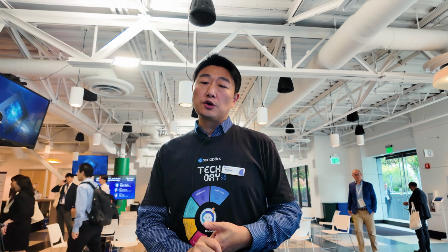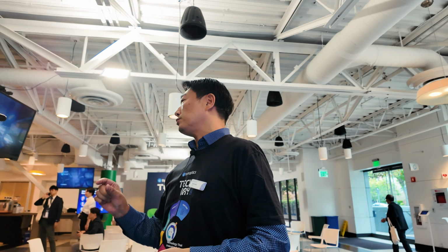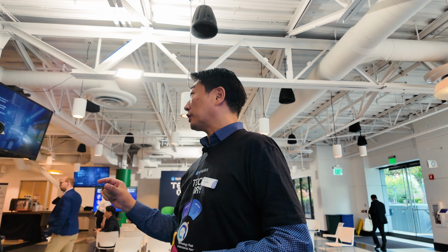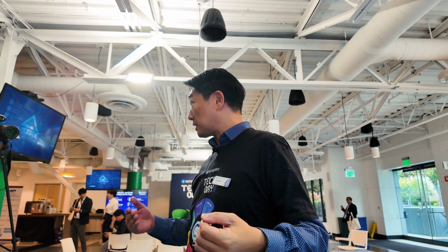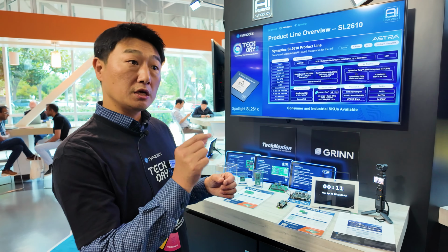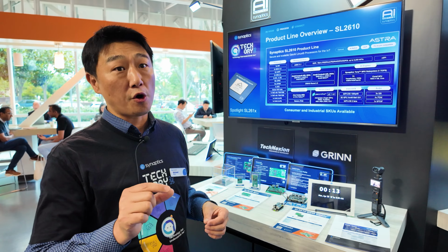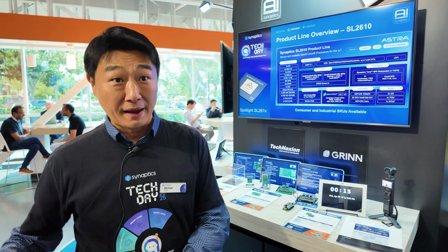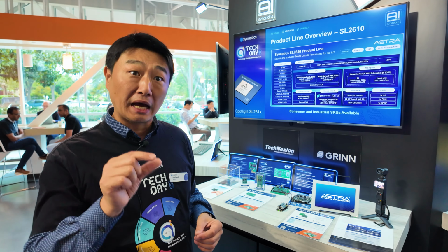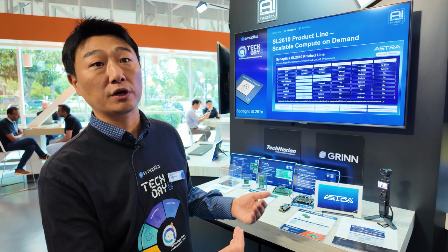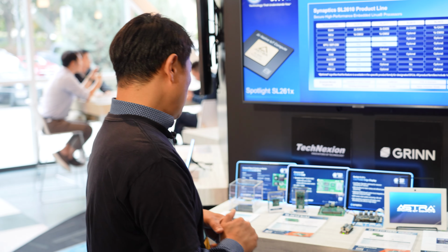And is this a completely new architecture in terms of the low power mode? Yes. Using M52 as a system manager is a new architecture design we added with the 2600 family, and we will carry this same design in our future generations. This M52 gives us more ways to control the power because the system manager can rely on RTOS, which consumes less power.